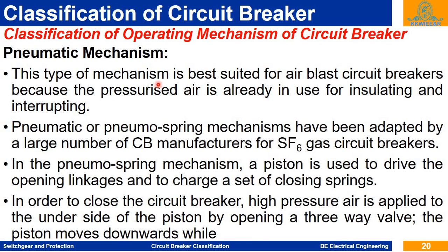This pneumatic mechanism is best suited for the air blast circuit breaker, because in the pneumatic mechanism you require compressed or pressurized air, and in an air blast circuit breaker, this compressed air is already available and used for insulating and interrupting. Pneumatic or pneumospring mechanisms have been adopted by a large number of circuit breaker manufacturers for SF6 gas circuit breakers.